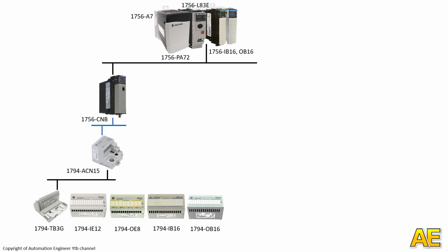And for each of these modules we need a base to connect with the ControlNet adapter. That base we can use model 1794-TB3G.